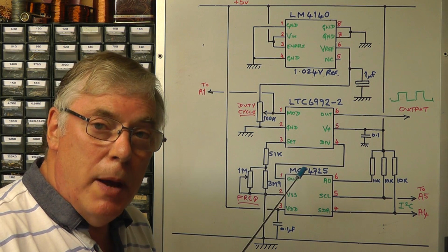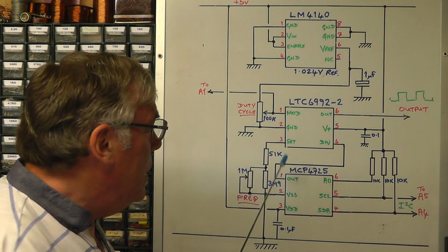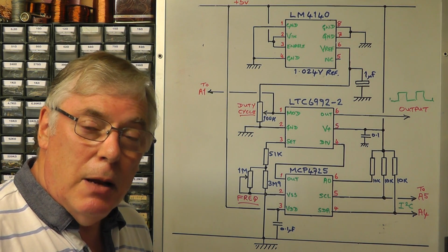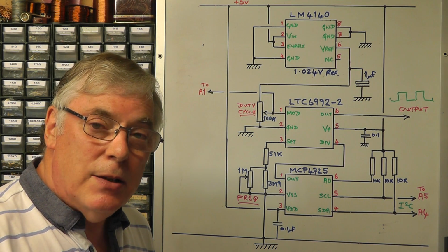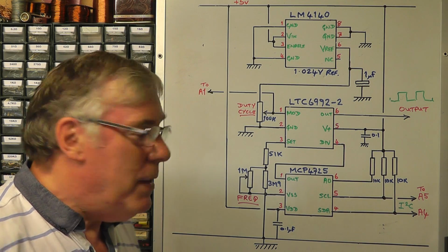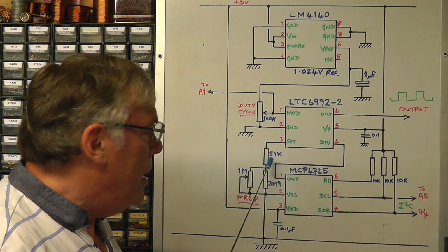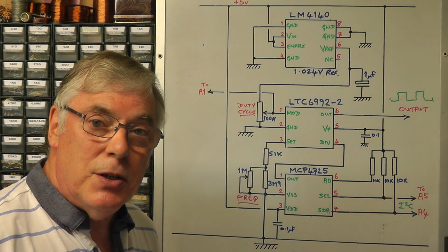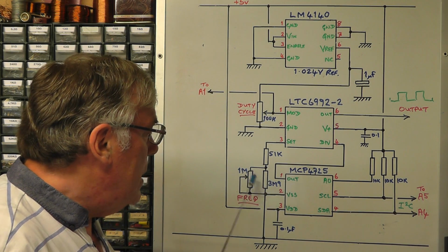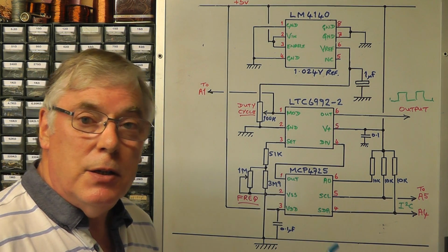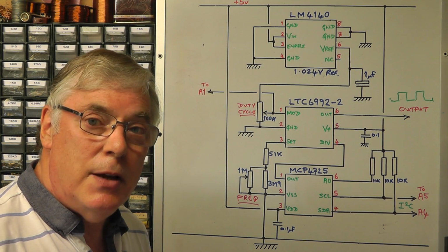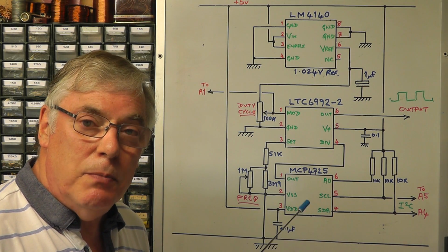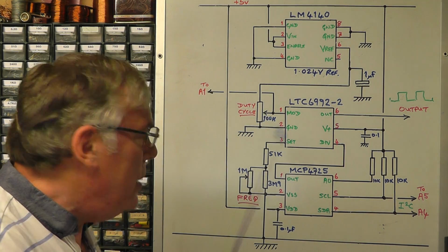Remember, we had a 1 megaohm potentiometer setting the frequency of this oscillator, but you'll also recall that when I explained a little bit about the IC, we may need to limit the upper and the lower limit of that range, and hence the reason why I put there a 51k in series with the potentiometer to limit the minimum resistance to around 50k, and I've put a 3.9 mega across it to try and limit the maximum resistance to around 800k. But we'll play around with that in a more practical sense when we get down to building the project. So we may change that later.